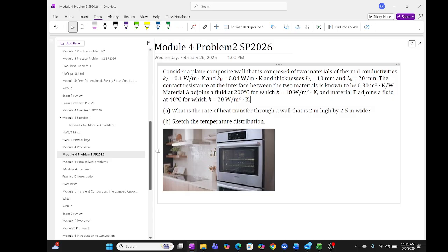You can't. Why? Apparently, to the naked eye you may claim it or it may appear that way, but in a microscope there are always microscopic gaps, right? And this microscopic gap is going to do what? Keep the air, and the air is not a good conductor. You understand? Any solid is a good conductor. Gas is not like solid.